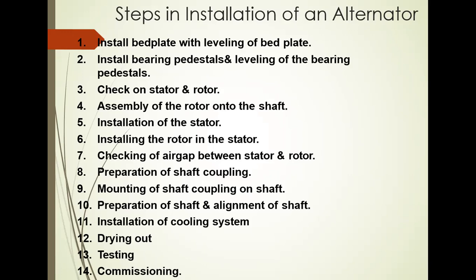Preparation of shaft coupling. Mounting of shaft coupling on shaft. Then preparation of shaft and alignment of shaft. That is the main thing, right? Shaft positioning. Then installation of cooling system. Then drying out procedures. After that, several tests are there that we have to take care of. Finally, commissioning of the synchronous machine takes place.